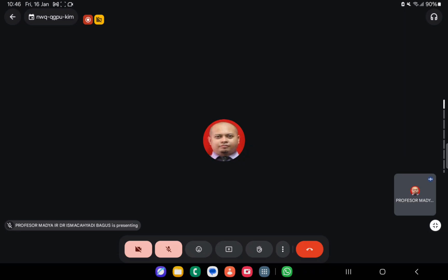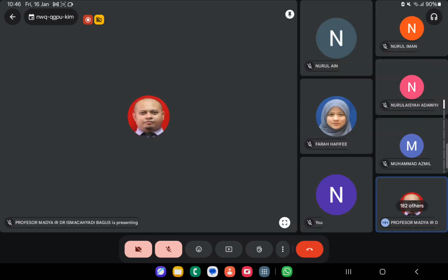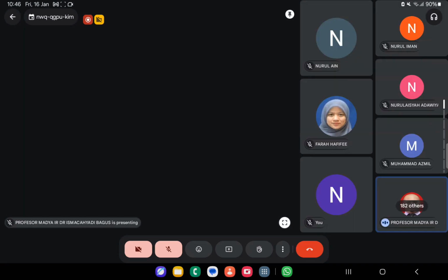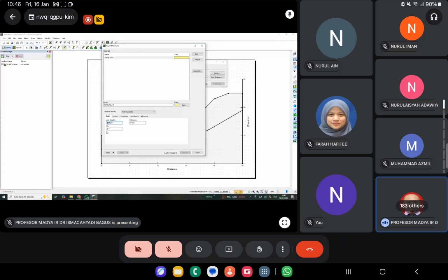Before ESA, effective stress analysis, the unit weight is from the soil properties. Most of the time on slopes, your unit weight is definitely more than 16 or 17, because most of these slopes are over consolidated. Most of them are over consolidated, so you will have direct cohesion.